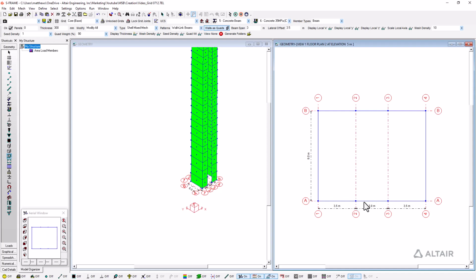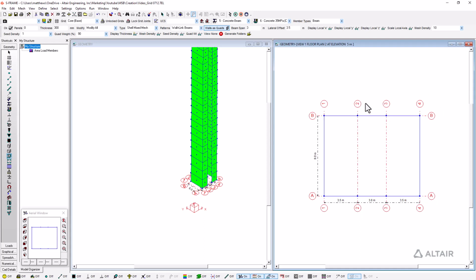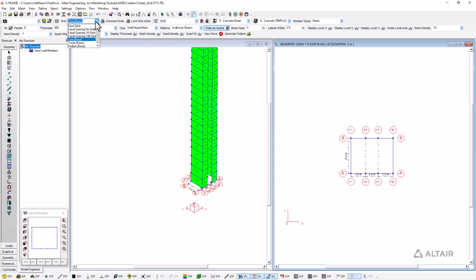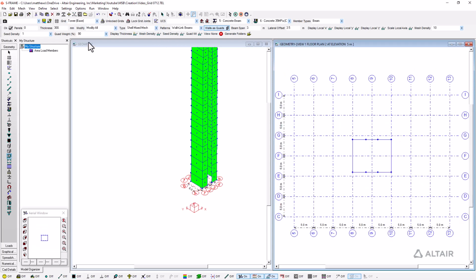And we do notice here that we have these joints where this type of geometry is starting to grow. So I'm just going to now focus on the creation of our tower geometry. And I do have columns that are going to be in line throughout the entire height of the structure. So I'm going to continue with that, but I'm going to switch the grids from the core base grid to the tower base grid.